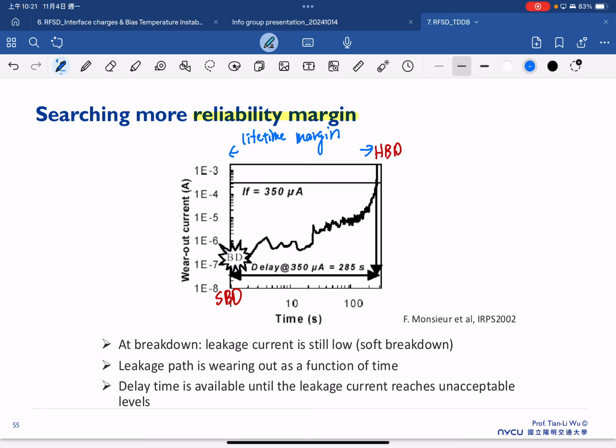Just like in this case, once we see the first signal of the soft breakdown, the increase of noise, we can understand that after 100 seconds the hard breakdown will come. So we should be aware that our device can only be used for another 100 seconds. That's pretty important because it gives a sense of prediction.